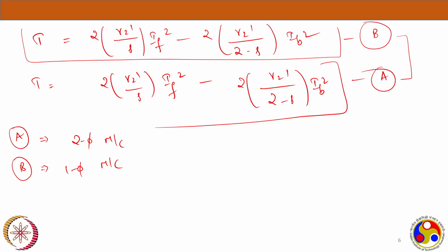So the circuit is now the single-phase induction machine equivalent circuit running on only a single winding, that is the main winding. There is no auxiliary. There is nothing. So we just did some modifications and the output we got is exactly related to a single-phase machine. That's what this equivalent circuit actually represents.